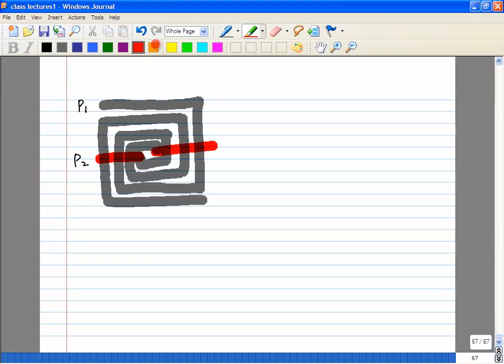So you want to take this across like this, and this would be your S1 and S2, right? This is fairly symmetric. Okay, you get the basic idea, right? So you have the same number of turns on both the primary and the secondary. You have the same number of metal layers, same width, same spacing, and you have an underpass in the primary, you have an underpass in the secondary, all at symmetric points. Is that clear?